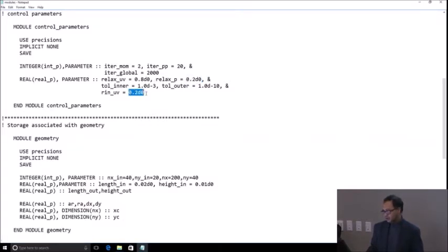You see, this is my inertial damping factor, 0.2, which is the same as what you used for the other problem. Now of course this problem has flow separation and recirculation zones and all that, so it's a little bit more complicated, and it has inlets and outlets. So that's pretty much what it is.